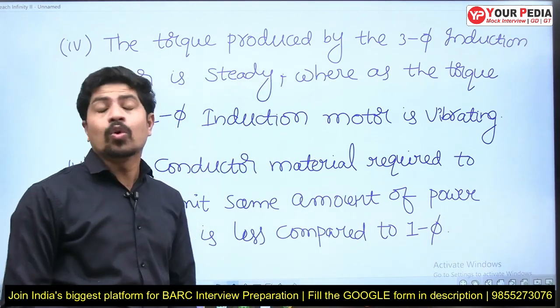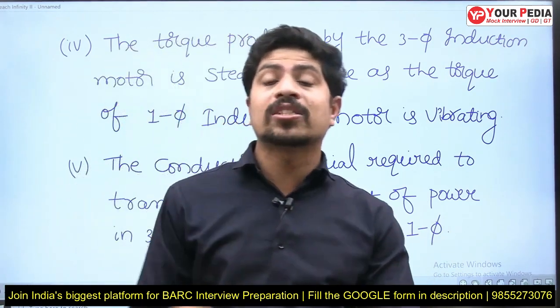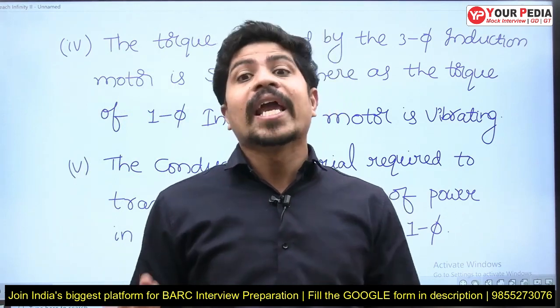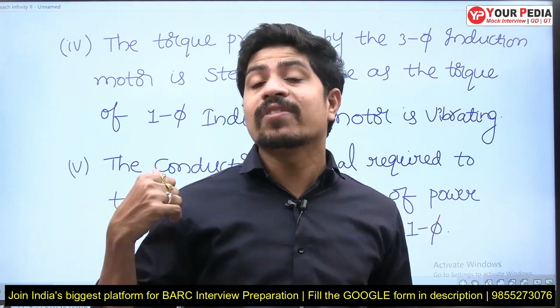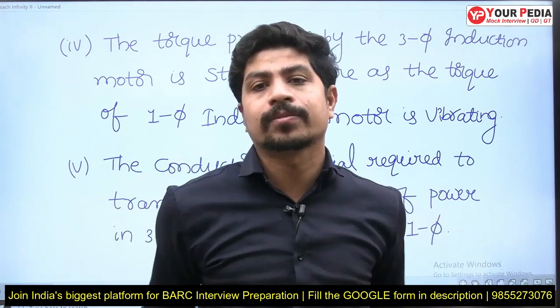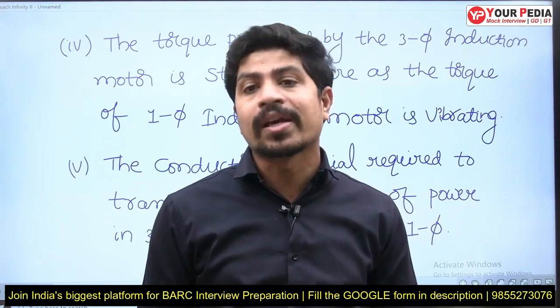Means if you want to transmit 100 watts of power from one place to another place, if the conductor material required by three phase is some 100 kg, then single phase requires more than that. Unnecessarily cost is going to increase.